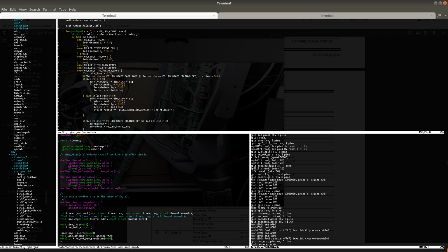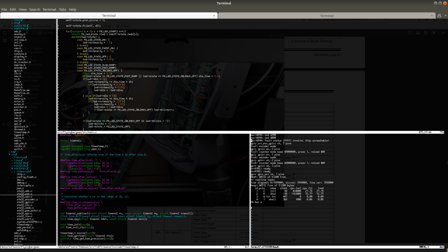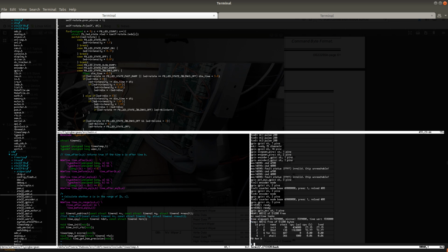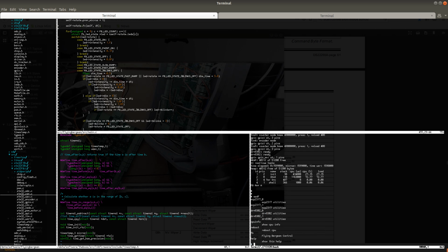I think that using a debug console is a very nice way to debug an embedded board. You can easily add commands to the debug console. You can debug different peripherals connected to the board. For example, here I have several commands that are registered by the device drivers of this board, and I can debug the low-level stuff that is going on inside those chips quite easily by just adding new commands that allow me to do that.